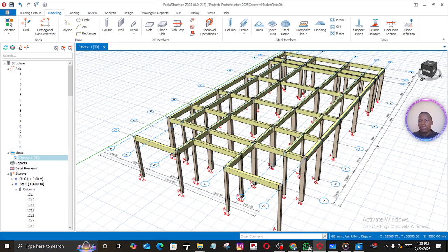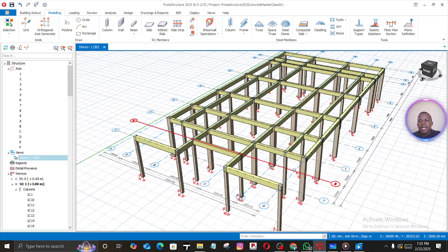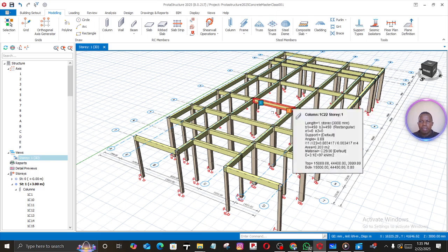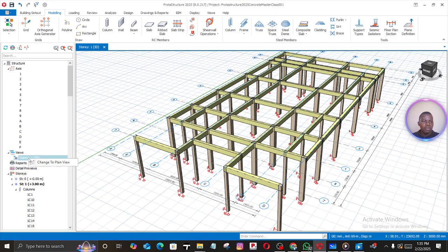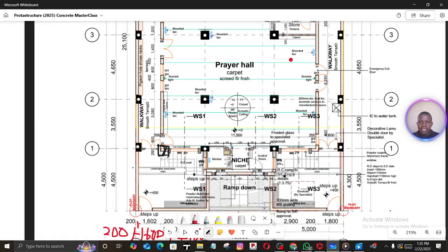So what we have to do, we have to add some basement here. We can add it later. We can simply add some basement below. After adding the basement, we add some shear wall here. I think we will come back to add the basement, but let's consider adding the shear wall on here. I mean the lift. So our next will be on how to model that lift. Let's go to plan view. Go back to our architectural design.